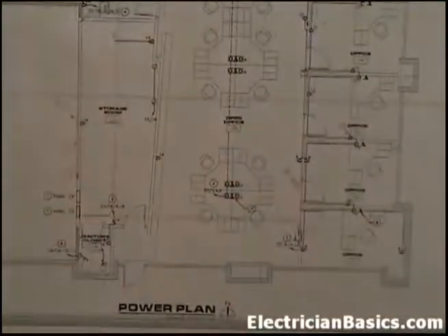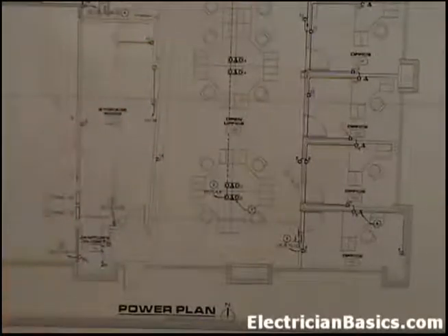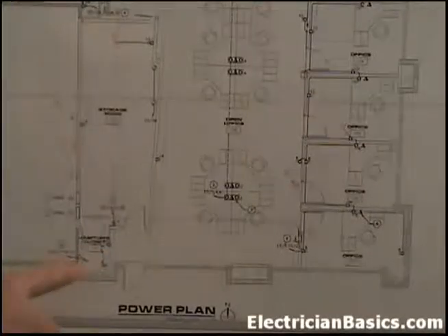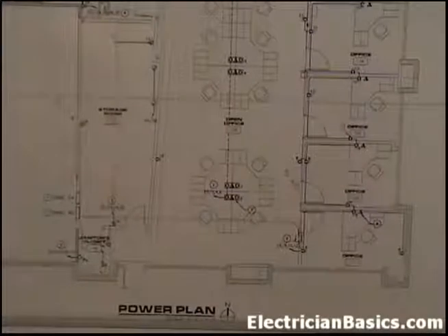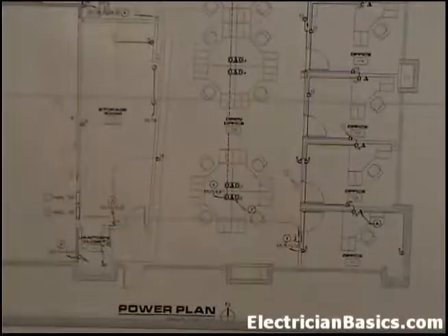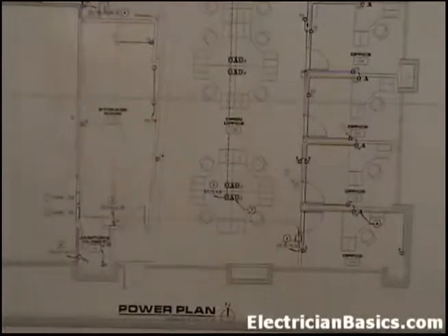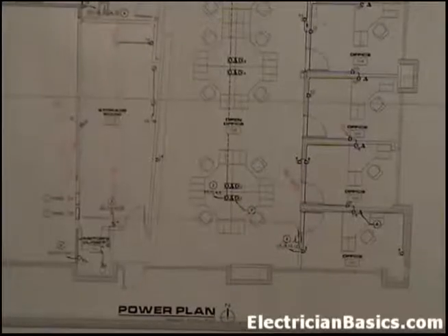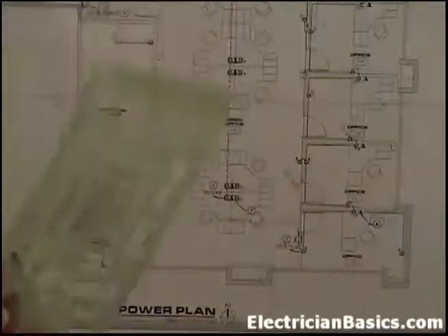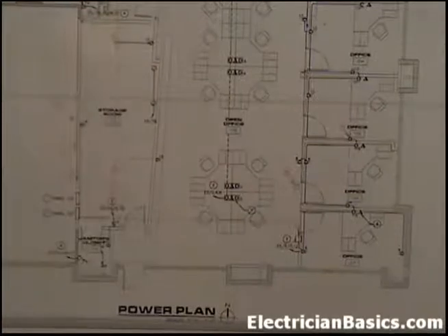We're down here at the bottom of our sheet. On our prints, we have our black lines showing our conduits, the pipe between conduits, throughout, and showing home runs. A red line shows how things were built, and sometimes things are a little different. I've drawn in some red lines with a pencil, or a red pen. You can take a mechanical pencil, pencil it in first and then go over it, and you can even use a felt tip marker. I also like to use a stencil when I make boxes and straight lines. I've seen some people just draw the lines and they're not too straight. For your boxes, you can get away with it if you're neat without stenciling it, but I prefer to stencil it.